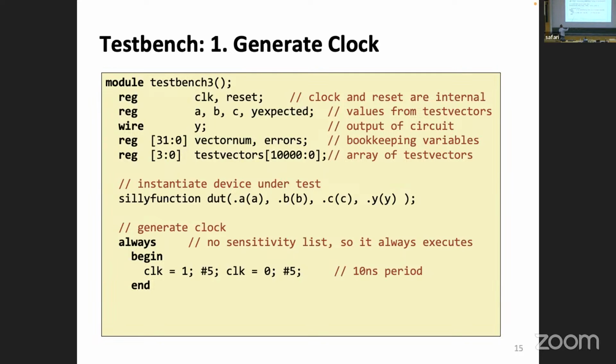Okay, since we only care about the rising edge of the clock, so this is what we were talking about here. I want to generate this for a period of 10, and at some point this has to fall. I don't really care so much that it is at 5, but why not? Let's be nice, let's be symmetric, let's not go crazy. It's nice, you know, like symmetric. If I were using the same amount of rising and falling edge flip-flops, maybe I would have said, I want to keep them balanced. Right here, it wouldn't matter. Oh, people are not so convinced.